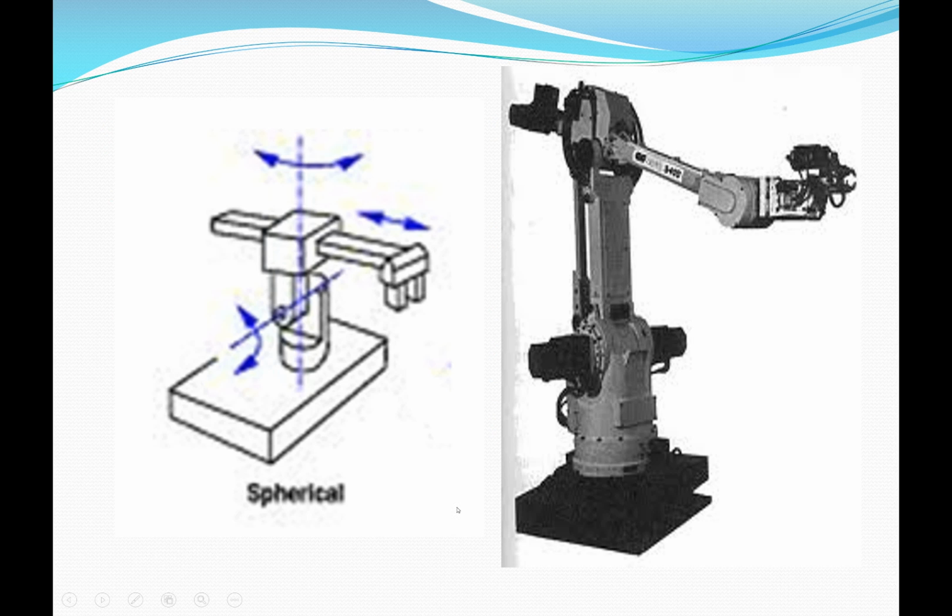The Polar robot, again, this one has nothing but rotational joints. Well, actually, this is a prismatic joint if this one goes in and out right here. This one could be going in and out, so that would be a prismatic right there. This is a rotational here. This is a rotational here. This is a rotational here. And this is a rotational that goes up and down.